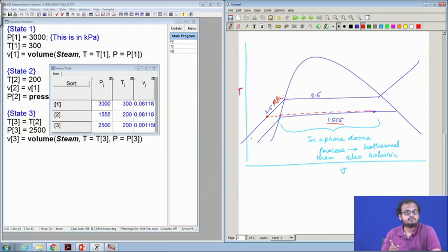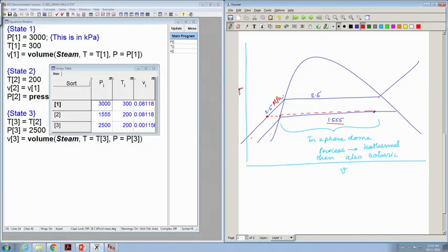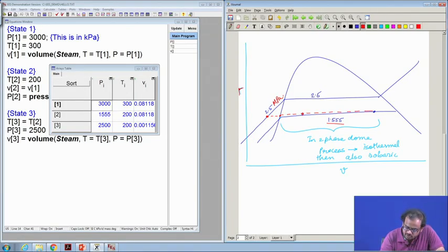If there was no increase in pressure and it was compressed, then it will indicate that you are still in the two-phase zone. So, for example, if the compression was done up until this point, if the compression was isothermal, then you would see no change in the pressure, because you are still in the two phase region.